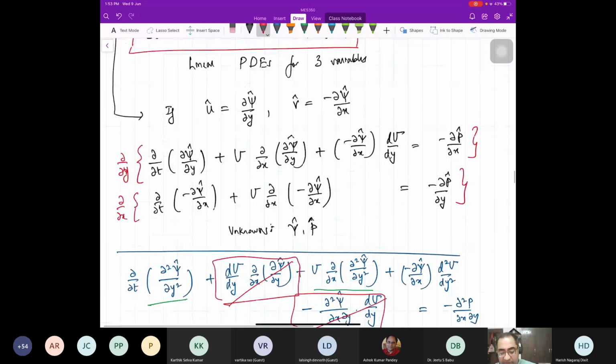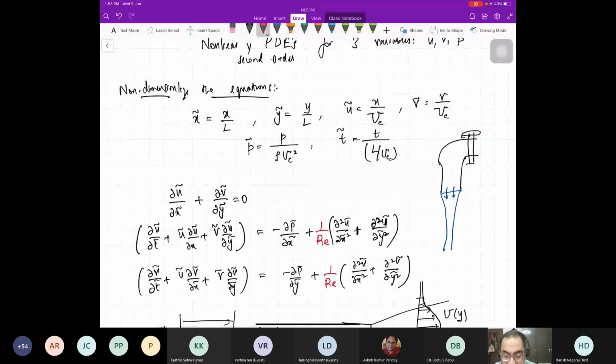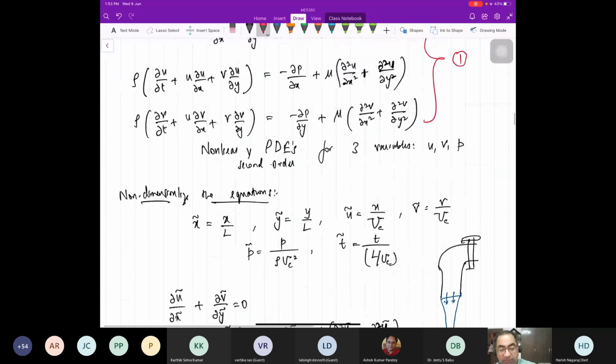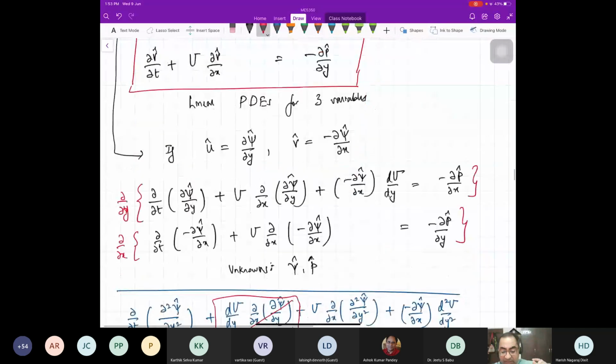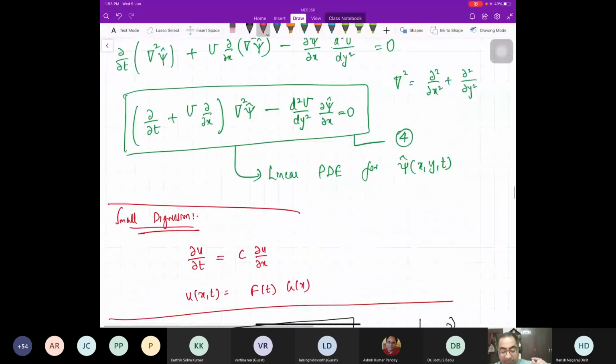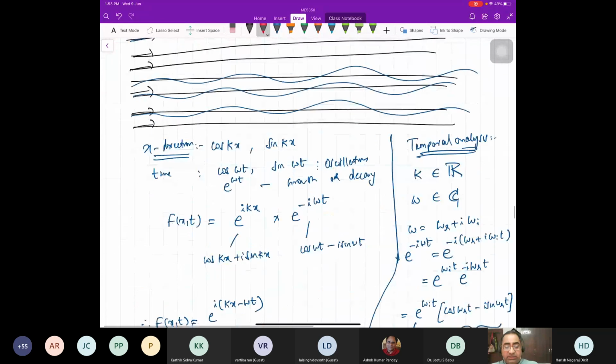which is called the Rayleigh equation. So just to reiterate the key steps, we started with Navier-Stokes. Navier-Stokes equations are nothing but nonlinear PDEs. We reduced it to a linear set of PDEs for multiple variables. Then we reduced it to a linear PDE for a single variable. And finally, we reduced it to a linear ODE for a single variable. So that's where we have gone. We've come from a nonlinear PDE to a linear ODE using a sequence of steps. Each of those steps is built on certain assumptions and simplifications. And once we have this linear ODE, then there is hope to do some analysis.